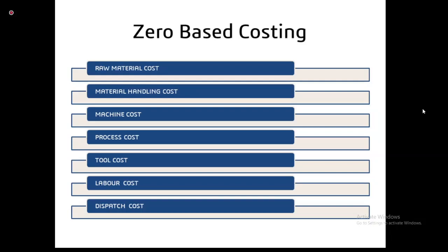Whenever I am doing zero base costing, I have to consider the function and the need of the component and of the product. Means what? For example, if I am doing the costing of a shaft, I need to understand the functioning of the shaft. Is there any heat treatment process carried out on the shaft, how many RPMs are coming on the shaft, what is the equal mass distribution load on the shaft. Wherever the bearings are going to be mounted on the shaft, should I go with the grinder, or should I just machine it with the help of lathe machines?